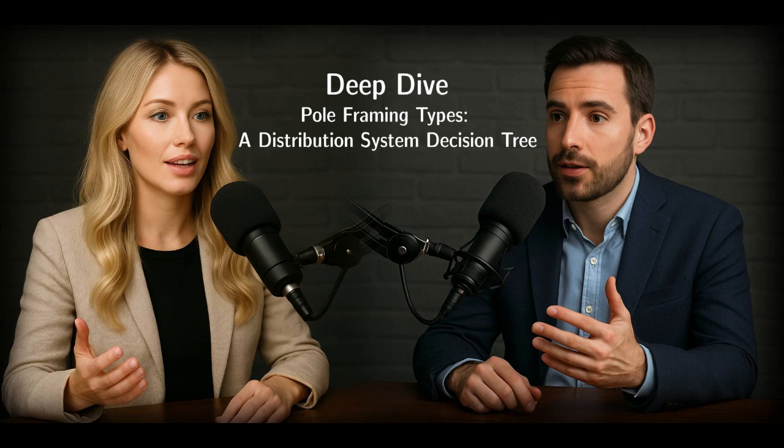This isn't just a design choice. It's an absolute necessity structurally. You'll recognize it by its sheer robustness. Often multiple crossarms, heavy-duty steel hardware, and almost always substantial guying. We're talking multiple down guys maybe, or perhaps extensive bracing, visibly countering that immense tension from those terminated conductors.